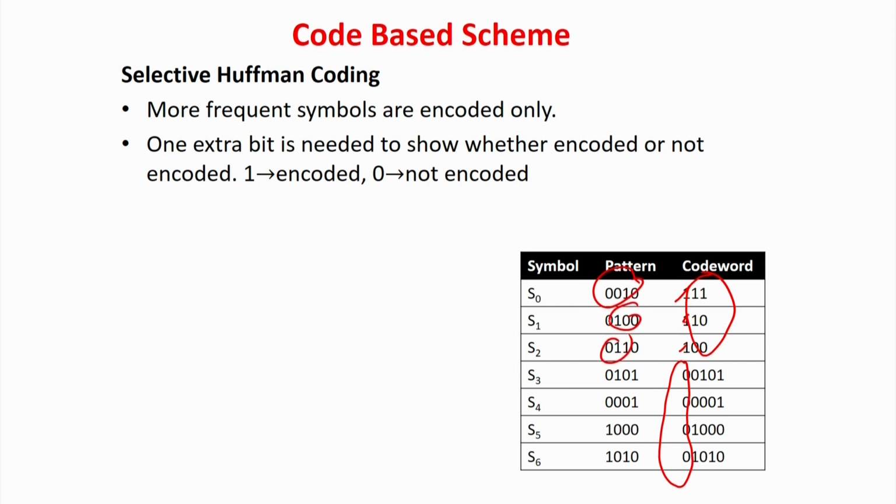So what is the gain? The gain is that your decompressor circuit inside the cut will be of smaller area. But what is the cost you are paying? Certain rare patterns will take a higher channel width from the ATE, so the cost will rise, but not by much to worry about, because those are very rarely occurring patterns.